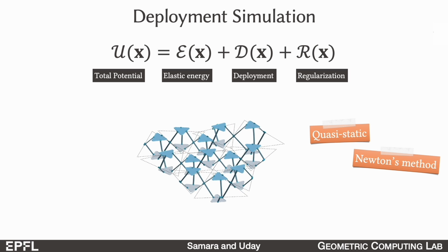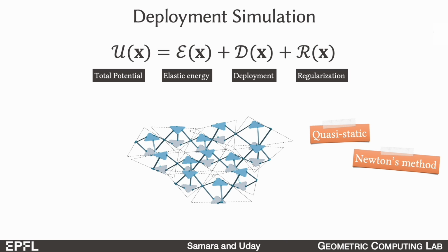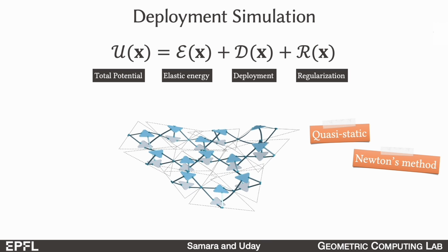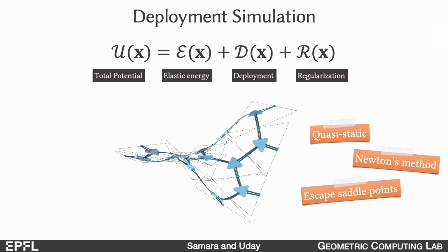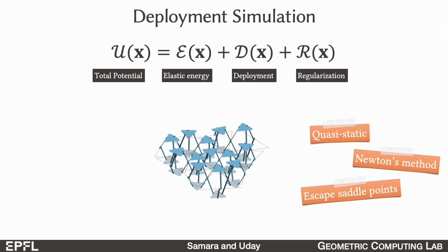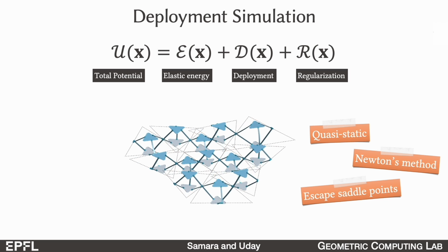For example, here when the structure opens up in plane and just before it buckles out of plane, without any perturbation, it wouldn't know which way to buckle. Our algorithm detects such cases during the equilibrium solve and uses the negative curvature direction of the Hessian to escape from the unstable states. To illustrate all these points better, we'll now show some recorded demos of our simulation framework.